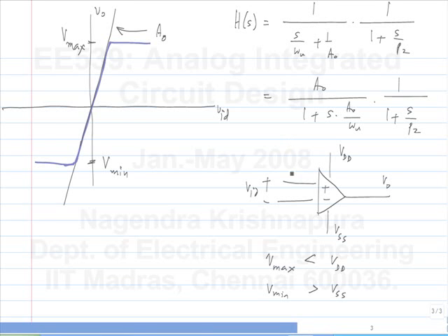What about the absolute voltage at this point? So far we only talked about VID, that is the difference voltage between the plus and minus input terminals. What will be the voltage at each of these terminals? You have built op-amp circuits, right? Like what is the voltage there at each terminal? Yeah. It will be 0 volts with respect to ground.